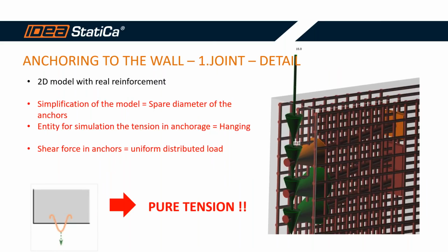It's the point. So what's the approach for simulating the transfer of the tensile forces in the anchors in the application Detail? We have to use some entity or some device for transfer of the tensile force, and it will be hanging load. The shear force will be transferred using a uniform distributed load on the edge of the wall.